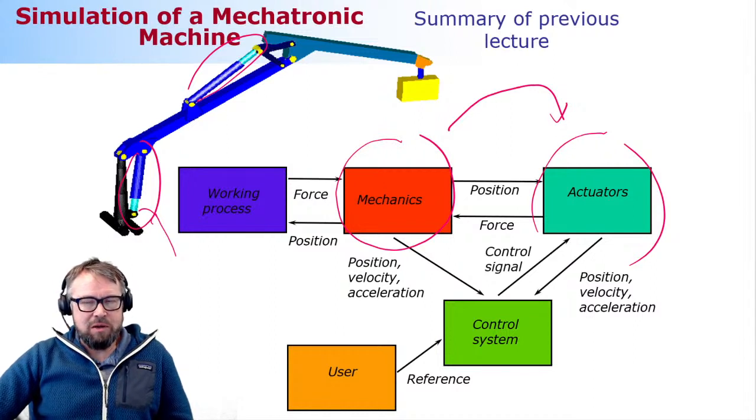And because of the low lubricability, you have to use some exotic materials in your water hydraulic components, like ceramics and such, which makes them expensive. So it's not as affordable as conventional hydraulics. And it comes with another drawback too.